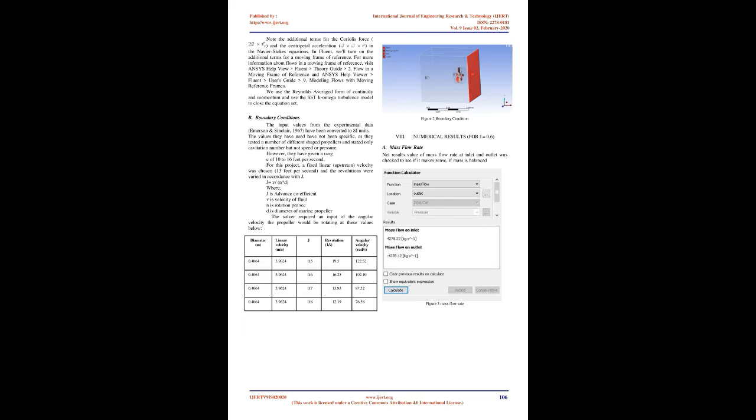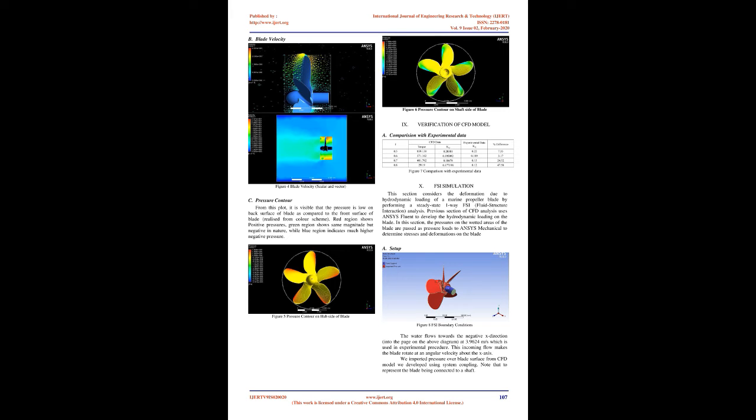7. Computational fluid dynamics analysis. A. Mathematical model, governing equations. The governing equations are the continuity and Navier-Stokes equations. These equations are written in a frame of reference rotating with the blade. This has the advantage of making our simulation not require a moving mesh to account for the rotation of the blade. The equations that we will use look as follows: conservation of mass.